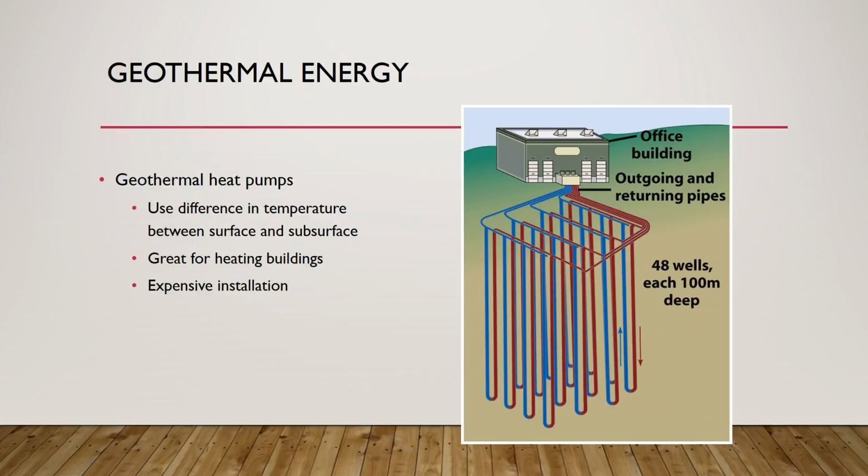Because it stays relatively cool compared to summer temperatures, they can pump air underground and use it as a heat exchanger, and the air that comes back in the pipes is much cooler than probably the ambient temperature. And likewise, in the wintertime, they can use the fact that it stays warmer than the ambient temperature to aid in the heating of a building.